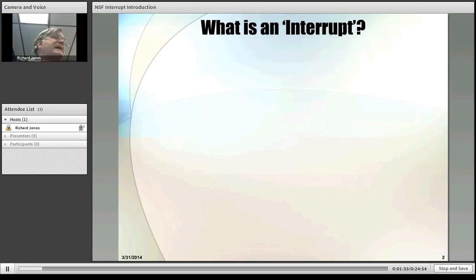So we would have something called the watchdog timer, which is running while it's asleep and is not dependent on the actual internal timers. It's separately controlled, and it uses very little energy while it's running. That watchdog timer would time out, the interrupt would be generated, and the system would wake up, look around, do what's necessary, and go back to sleep.